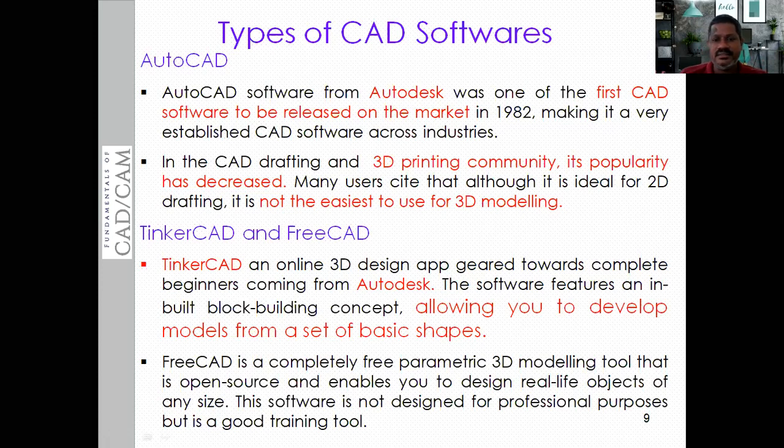As I said, by using this AutoCAD software, it is not possible to create complicated three-dimensional drawings. You cannot generate complicated non-uniform surfaces, B-spline surfaces. Simple three-dimensional drawings you can generate using AutoCAD. Regular shapes like the cube, rectangle, sphere, simple toroid, all those you can generate directly. Wedge you can create. So AutoCAD is used for this purpose, basic drawings.